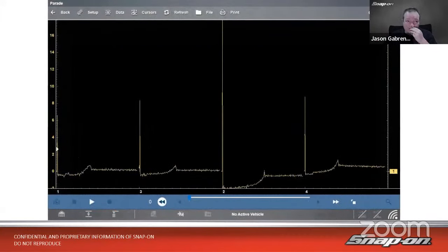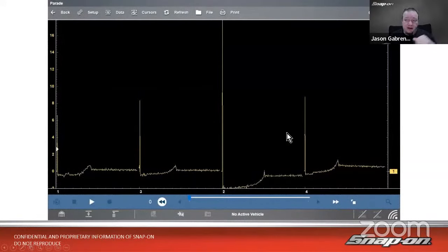Here's an example of a bad pattern. I would not want to see this. This would indicate a problem with the vehicle. So I captured these while I was in the middle of doing a tune-up to the car. And I had about 120, 130,000 miles on the plugs. Don't quite remember how many it was when I changed them, but I thought, oh, I need to change the plugs. Perfect time to do this because I can see the difference between fresh plugs and old plugs.